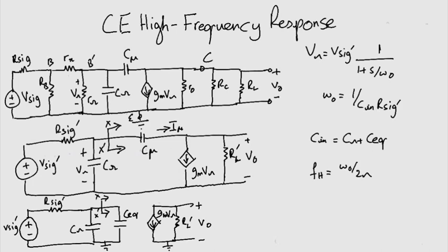It is the Miller effect that causes the common-emitter amplifier to have a large input capacitance C in and hence a low FH. Again, if you see in the instructor's notes, we have a lecture from the MOSFET module where this is touched upon in more detail. You are advised to look at it if you haven't done so already.